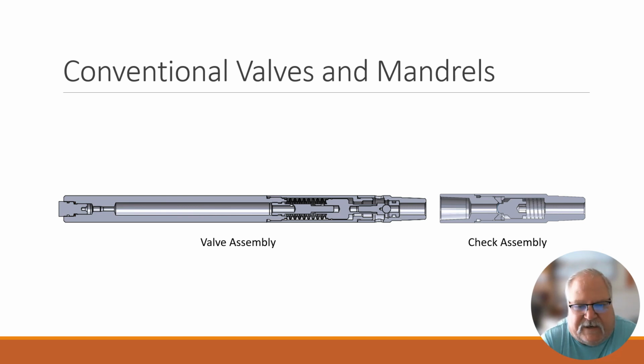But basically what we have here is you've got this valve. Here is your dome you fill up with nitrogen, which then puts pressure on these bellows. These bellows respond to the outside pressure, which comes through here and pushes and either compresses these bellows or extends these bellows as pressures go up and down. And if this valve gets hotter or colder, of course, this nitrogen inside here is going to expand or contract, which is also going to change that pressure.